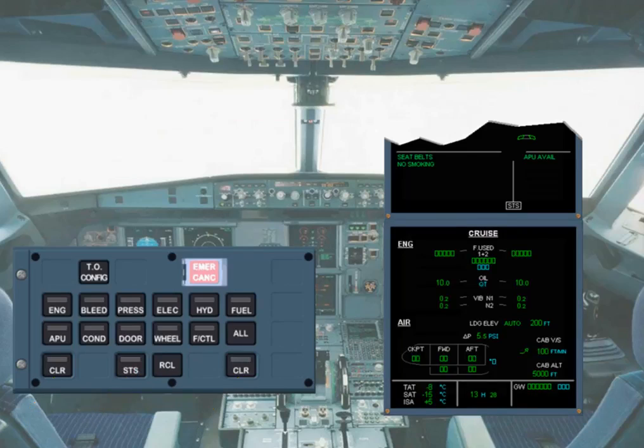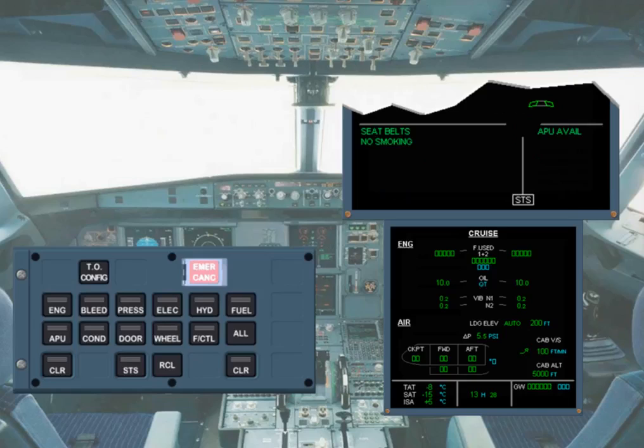Notice that on the engine warning display, there is a box status caption to tell you that there is information on the status page. On the Ecam control panel, there are no lighted keys. The Ecam actions for the digital flight data recorder fault are complete. So, as pilot non-flying, you should announce Ecam actions complete.